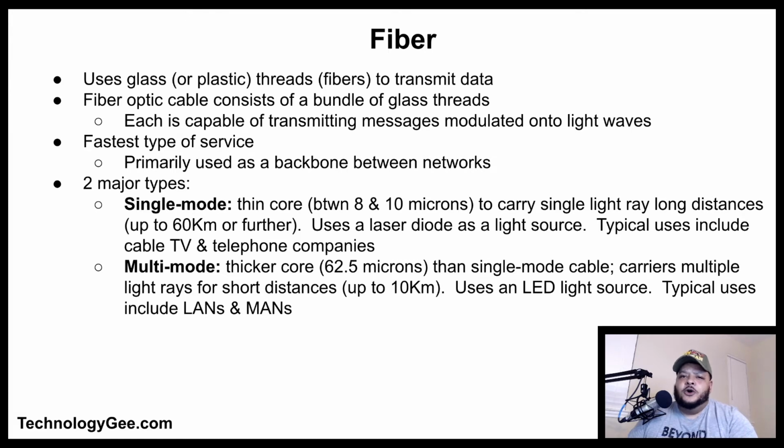You have single mode. This has a thin core between 8 and 10 microns designed to carry a single light ray long distances, up to 60 kilometers or further. Single mode cable uses a laser diode as a light source. Typical uses include cable TV and telephone companies.